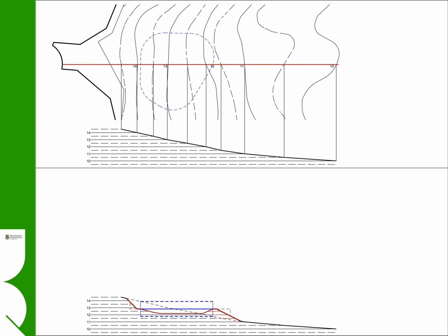In this slide we have a slope of the existing contour plan we constructed in the previous instructional. We have also roughed in the location of the new pond. Looking to the section on the lower half of the slide, we need to position the pond somewhere in the slope. We have already positioned it roughly in plan, and now what we need to do is to locate it in section. Given the aim is to minimize the amount of excavated material, we will propose a cut and fill